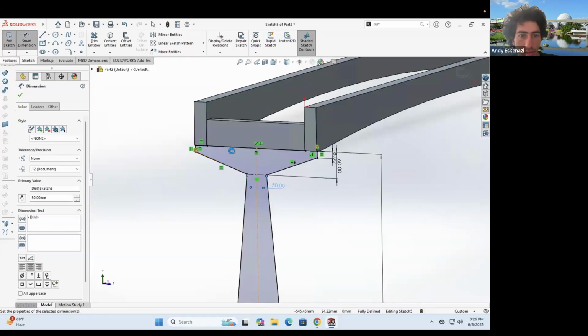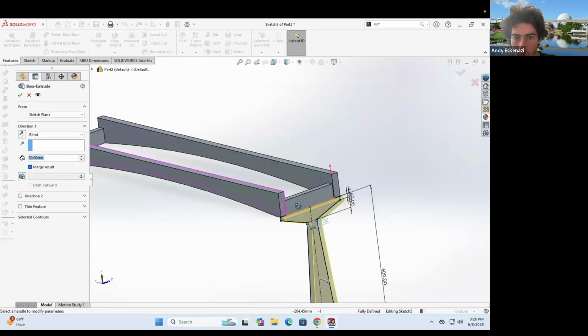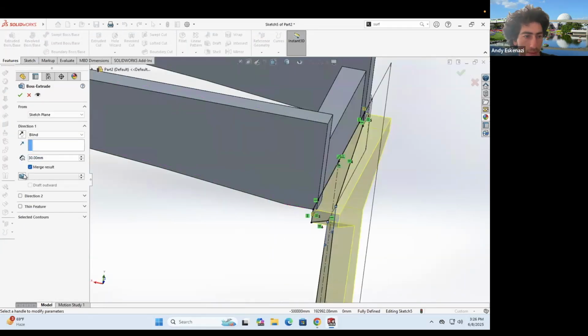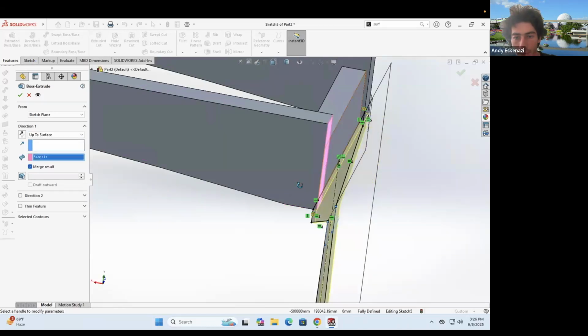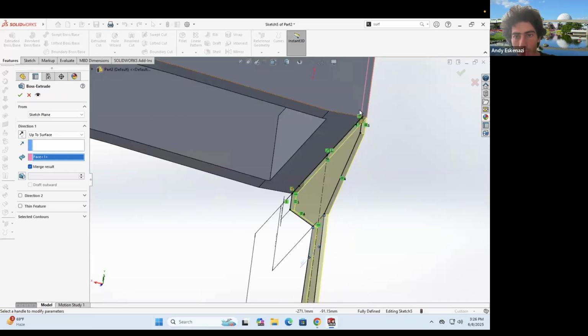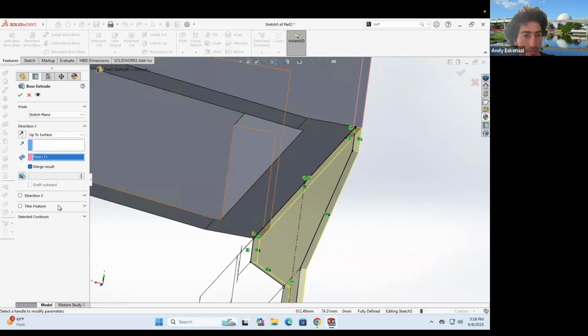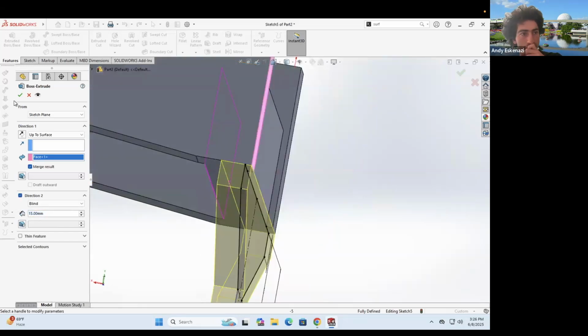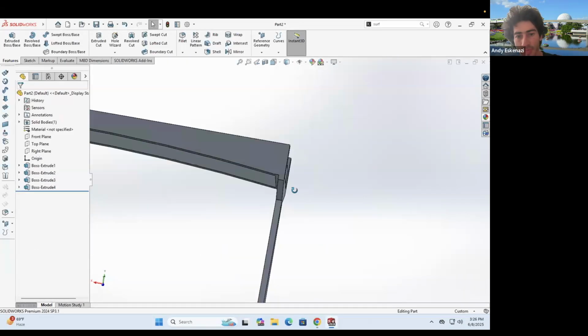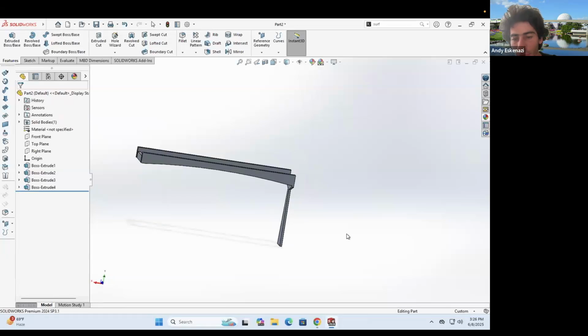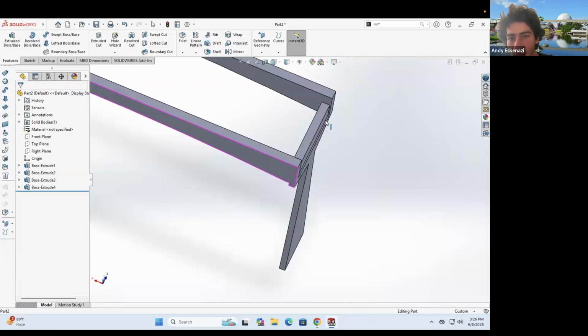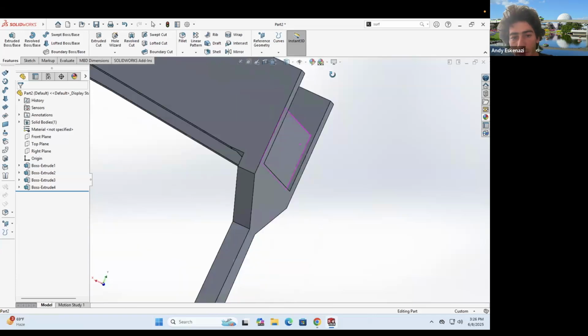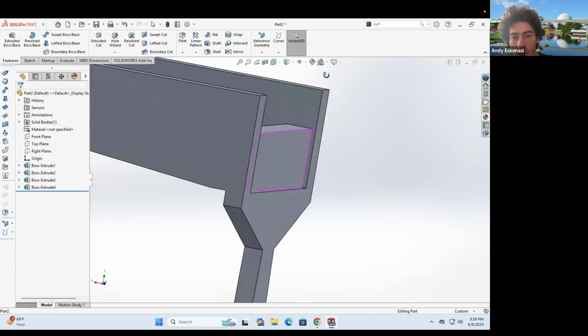And now this could be extruded all the way up to this face in here. Then in the opposite direction, maybe let's make it go up to 15, like that. Since this is gonna be symmetric anyways, right? So you're always gonna have one of these that is gonna be over there. We have this nice beam that's coming out like that.